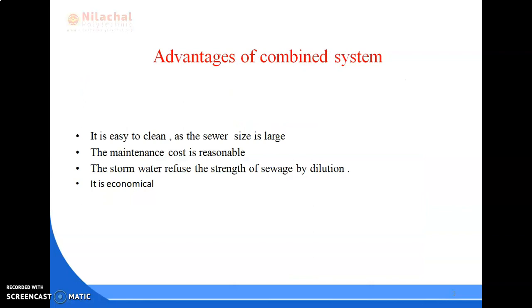Advantages of combined system: it is easy to clean as the sewer size is large. Also, the maintenance cost of this system is reasonable. Here the stormwater reduces the strength of sewage by dilution, and also this system is economical.